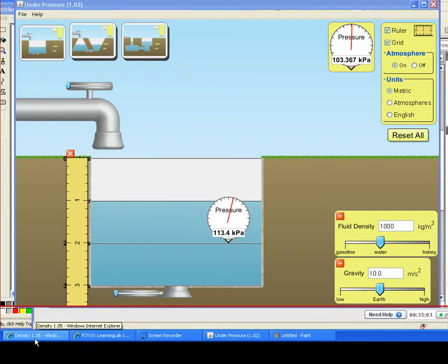Okay, that's the correct answer, Alicia. So again note that we are taking away 2 meters of air and replacing it with 2 meters of water. So it's going to be the old reading, which was 103.43, plus 2 times 10 for the 2 meters of water, minus 2 times 0.012 for taking away 2 meters of air, and that should give you 123.406. Is that clear, Divyangi?